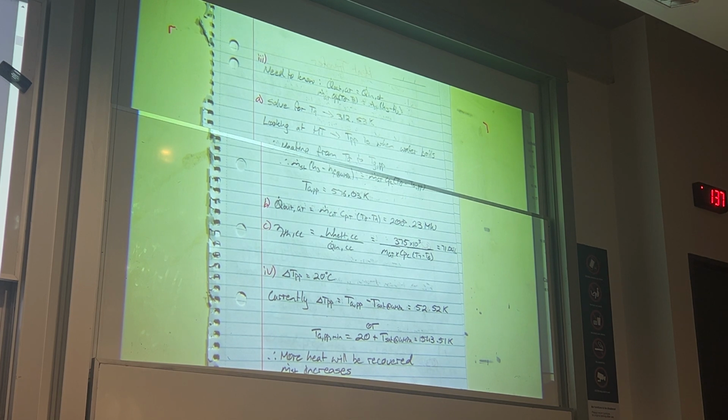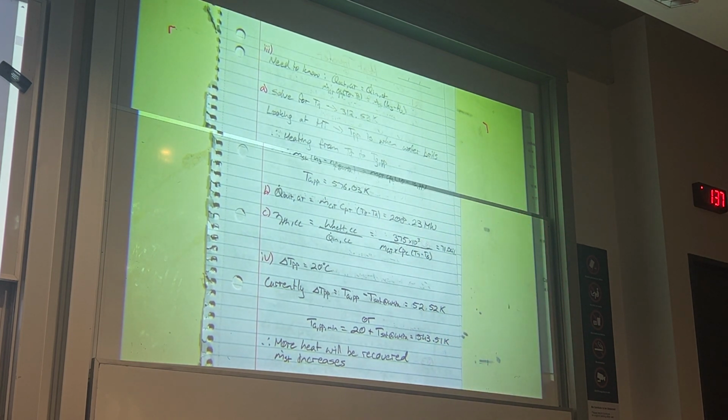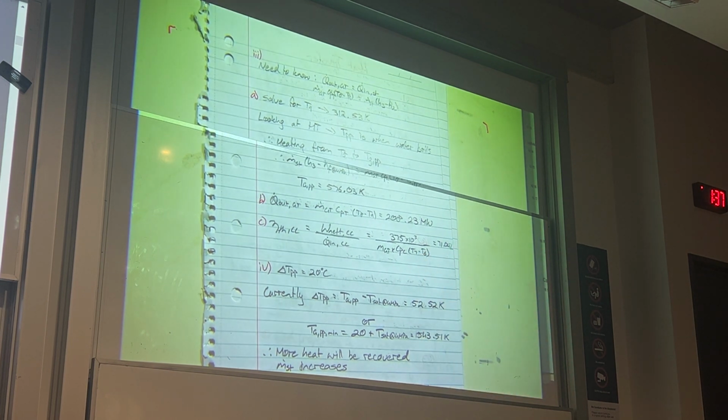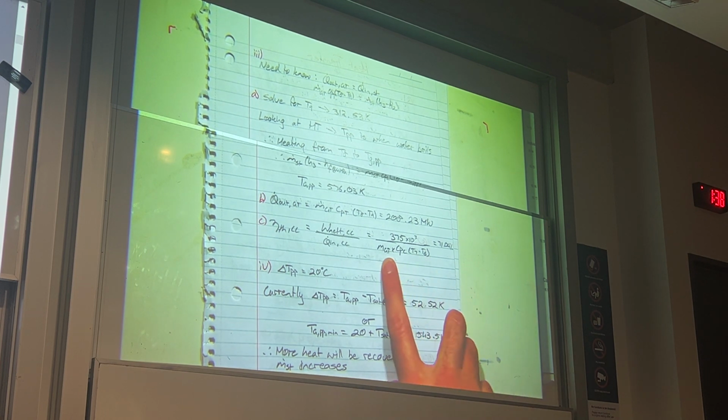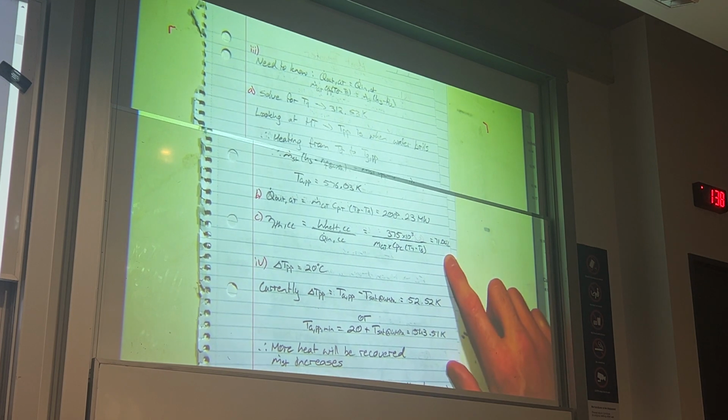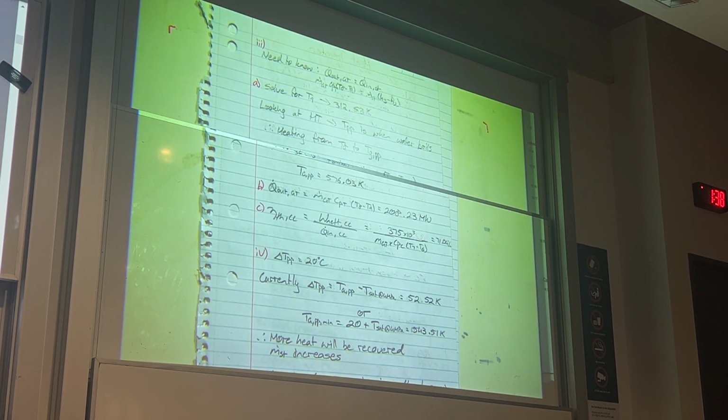And then we can just do the efficiency of the whole cycle. We're told the whole cycle produces 375 megawatts. That's why I've got that 10 to the 3. And then the only heat we put in is in our combustion chamber up here. So make note of that. I think what they're trying to do is trick people up into thinking there's Q in in the Rankine cycle, but that Q in for the Rankine cycle is already within the cycle because it's just exhaust heat or wasted heat that wasn't converted into energy through our gas turbine. So we should only have one Q in term, which comes out as this, and we should end up with 71.04%.